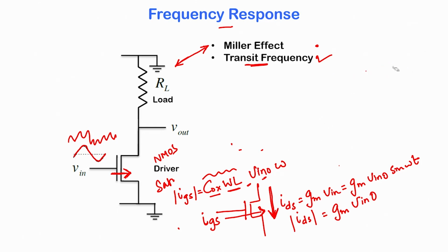And why is that frequency critical? Because at that frequency the leakage or the input resistance of the gate has started matching the effective resistance of the source to drain, which basically defines the maximum limit or the frequency to which you can push your device to operate.